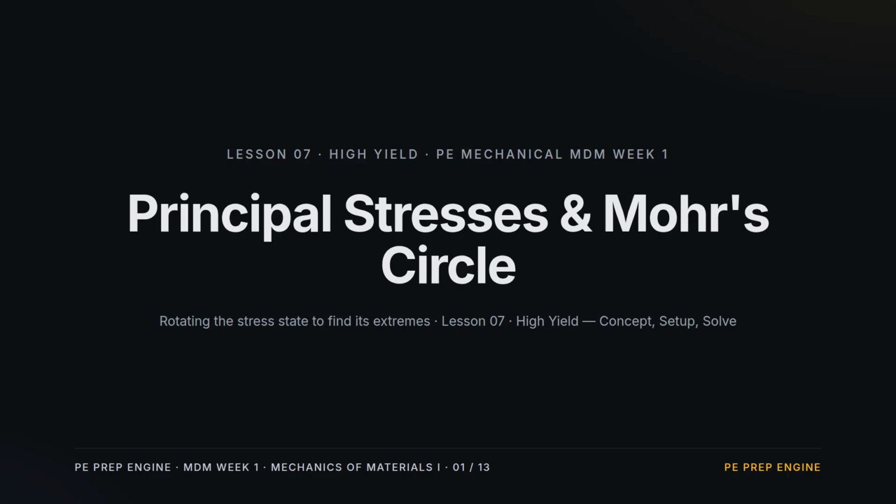Three one-line ideas. The principal stresses come from one transformation formula. Mohr's circle is that formula drawn as a circle with a center and a radius, and the radius is the maximum in-plane shear. Get those, and any plane stress point is a plug-in.